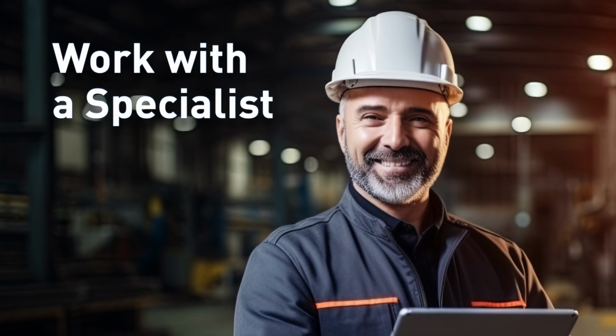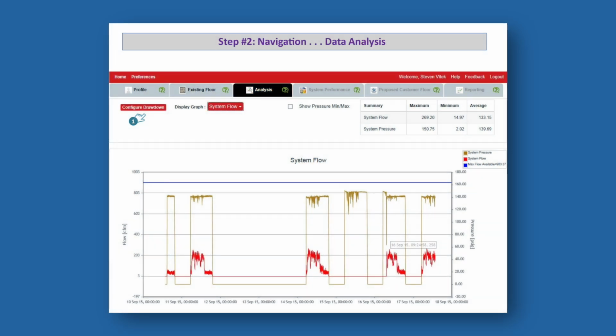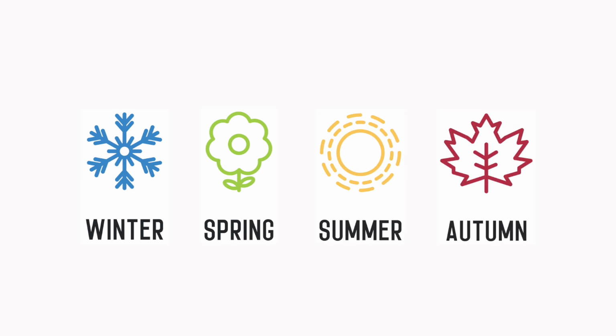The best source is to have a trained compressed air specialist perform a system assessment on your system. The system assessment provides accurate flow and pressure data. Temperature measurements of the inlet, discharge, and ambient air will allow the specialists to calculate dryer inlet temperature extremes based on seasonal compressor room ambient temperatures.